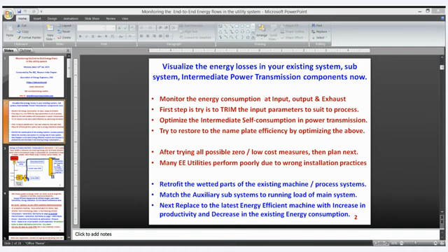Okay. The national T&D loss has come down from 35% to 15%. This is what we are trying to apply in the industry also. The end-to-end energy loss, in terms of end-to-end pressure drops and temperature drops, especially on the compressed air header. What is the pressure at the incoming? What is the pressure at the delivery point, at the machine?